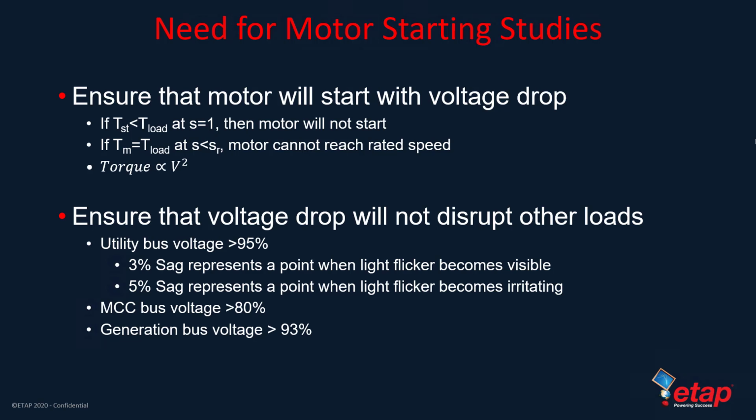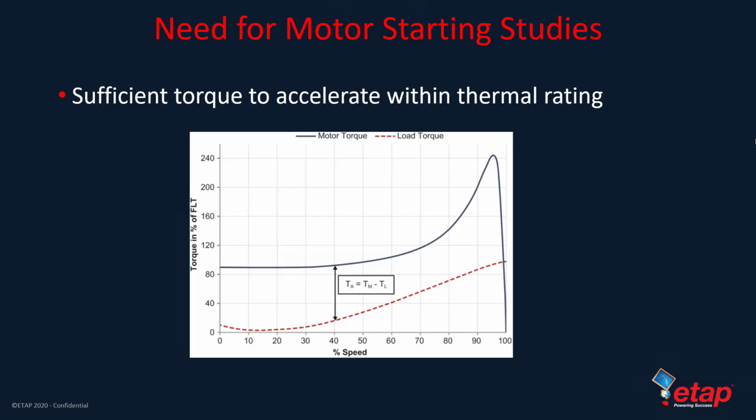Going back to item number 1, ensure that the motor will start with the voltage drop. We can see that if the torque load is greater than the available motor torque at slip equals 1, the motor will not start. So let me quickly introduce what that means.